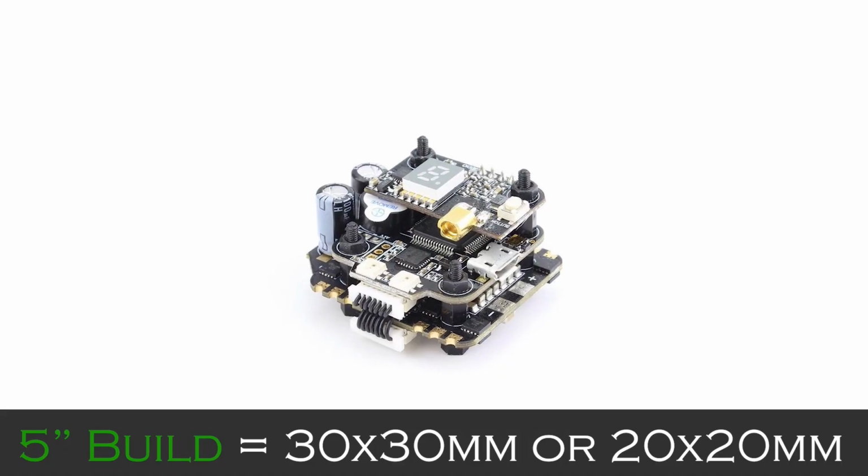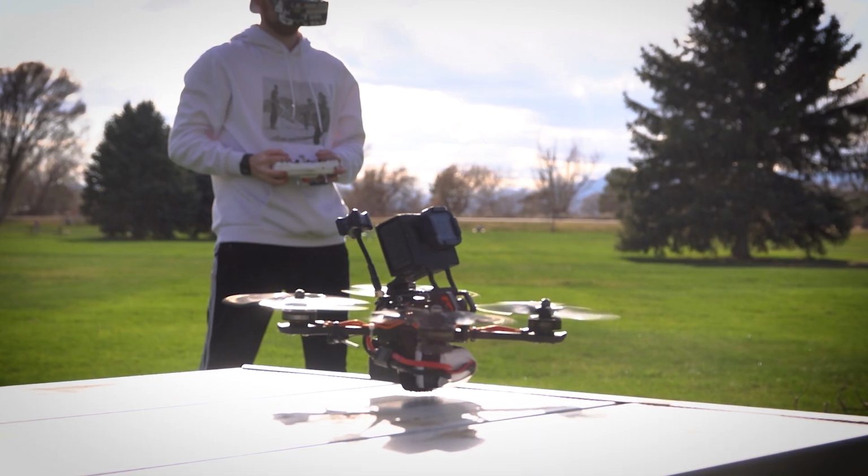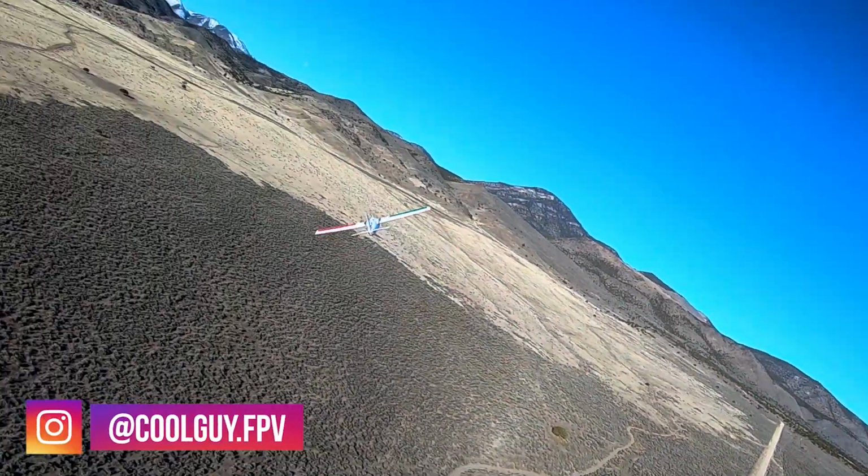However, another common size is 20 by 20 millimeter. For smaller drones, custom size and shape flight controllers will be available. It is generally advisable to place the flight controller at the center of the drone to ensure best performance. This helps the flight controller record the cleanest data from the accelerometer and gyro.